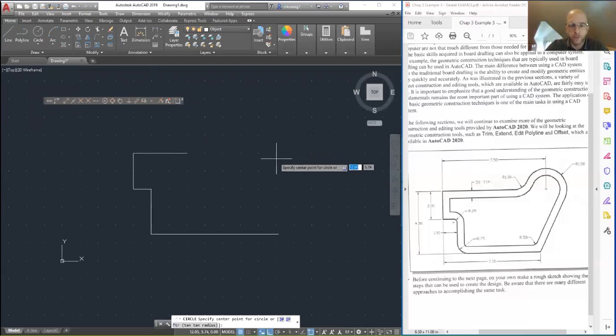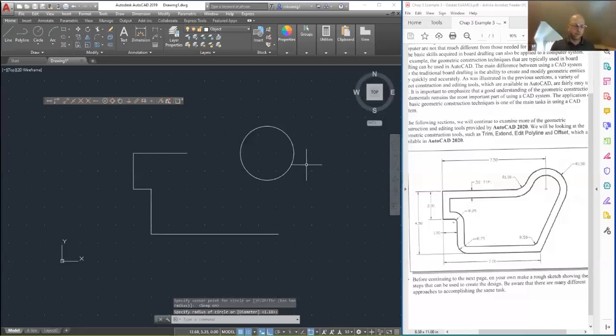And we're going to find the point using the grid snap. So I'm going to turn on snap to grid. And I'm going to find that point 11.5, 6. So I'm just interactively going to select the center. Now I'm going to interactively select the radius. So we need a 1.5 inch radius. I'm just going to snap to the grid. Give me 1.5. And do it this way, this way. Anything that'll give me a 1.5 inch radius. So again, anytime you're not entering values, it's interactive.